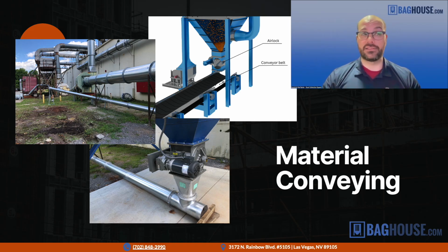So dust collectors in these kinds of applications, you see them sometimes in the form of bin vent silos, like we said. Other times you'll have round dust collectors that are called filter receivers, where you blow to them, or maybe they're a vacuum system pulling. These are essentially just baghouses that are round so they can handle higher pressures. But these systems, for all intents and purposes, function the same way as normal baghouses.